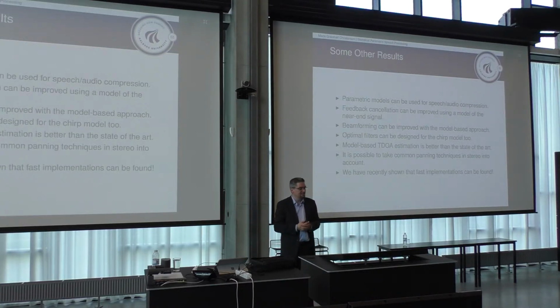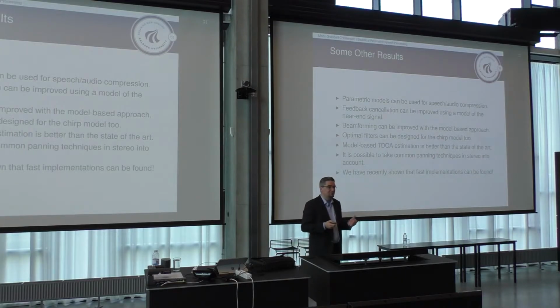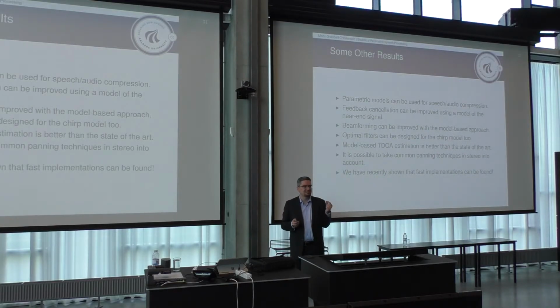And an interesting thing that we found out quite recently is that these optimal filters I talked about here can also be designed for the chirp model. And that's interesting because it means you can actually design optimal filters that take the non-stationary nature of speech into account. And that's not something you can really find out there, with the possible exception of Kalman filters.